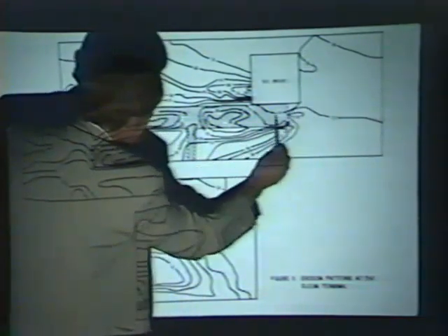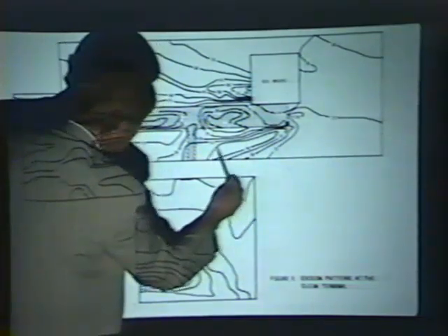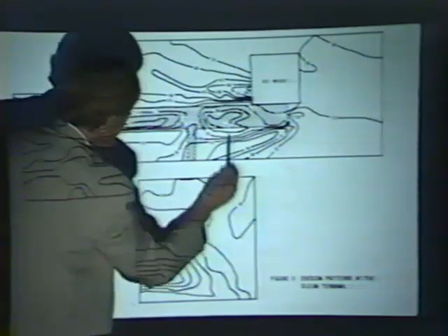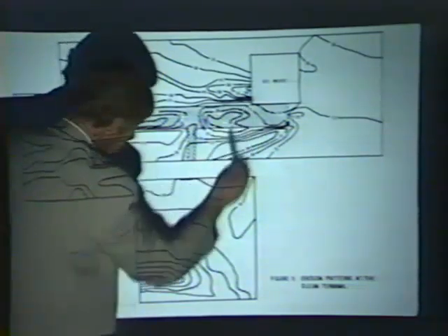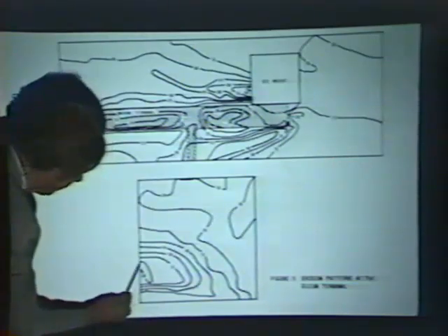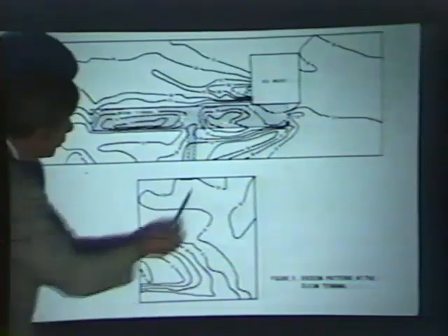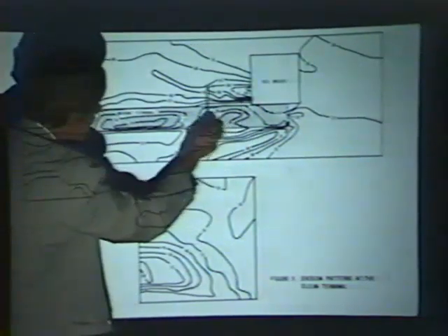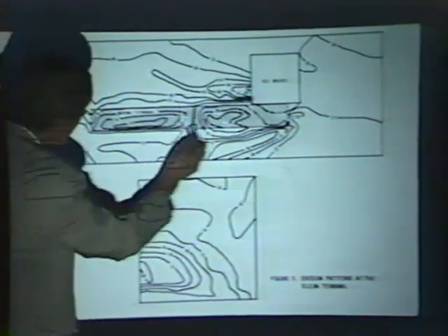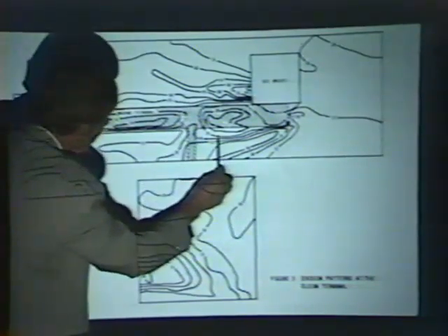Here's a 60-foot contour, 55-foot contour. So there's really deep grooves here and here. And then it's 35 feet here and 25 feet here. Actually, it fills in more along here than shown here before they dredge it. They'd like to keep 40 feet of depth along the side.